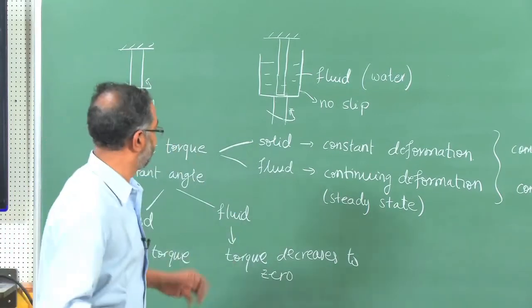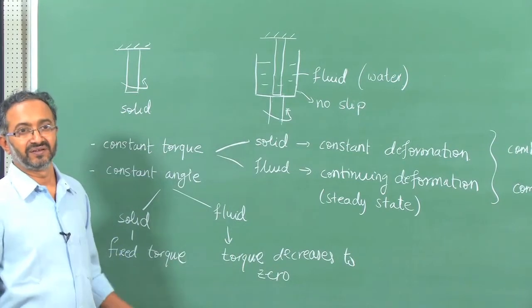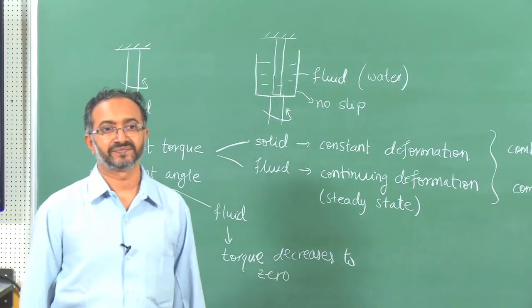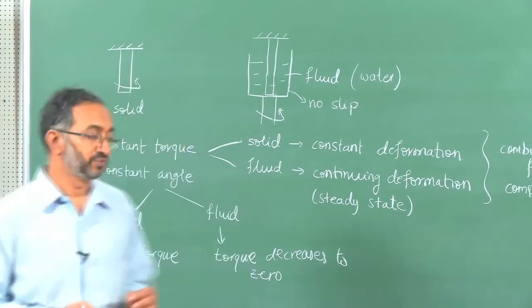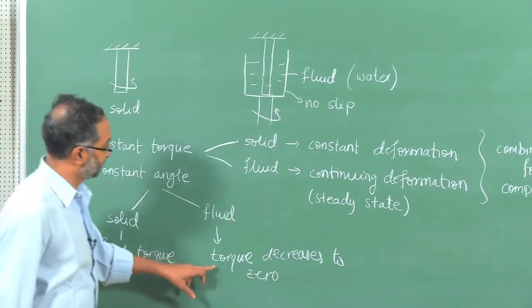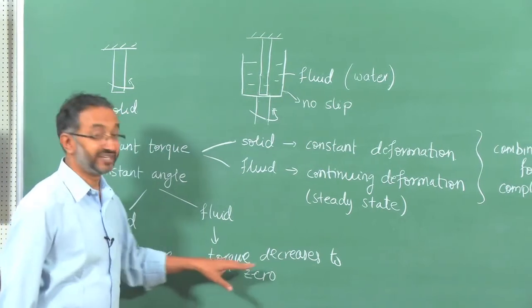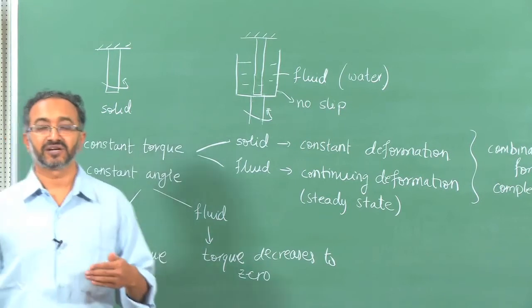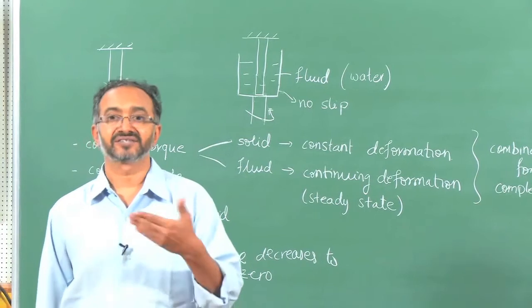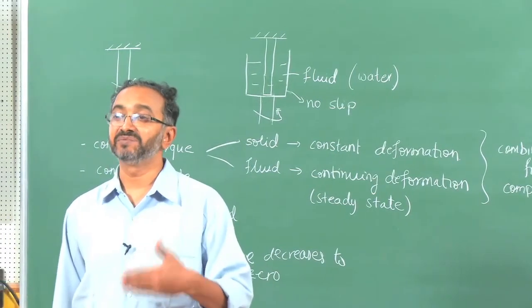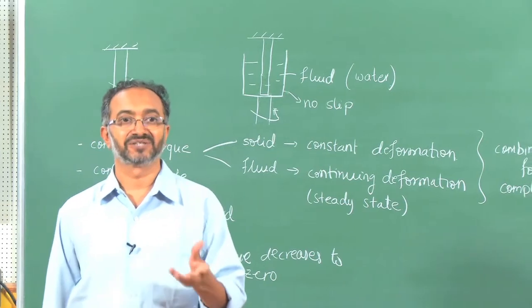So during the applying part, what happens if this is a complex fluid now? What would we expect? Combination of both. Yeah, again it will be a combination of both. So what you would see is that the torque would decrease, right. That means the material is able to dissipate energy at a certain time scale, and that time scale will be different depending on what the internal mechanisms in the material are.